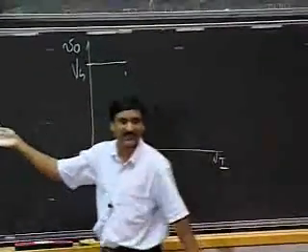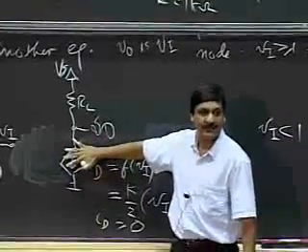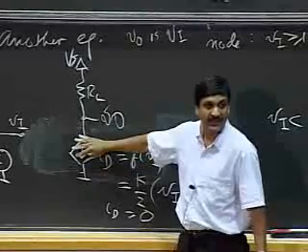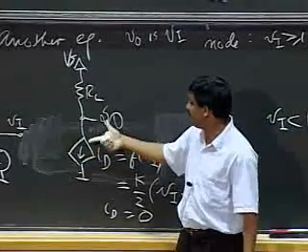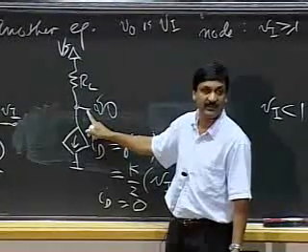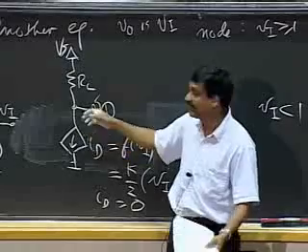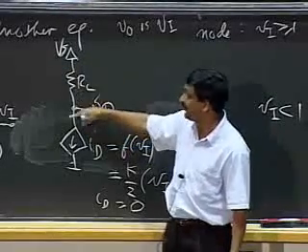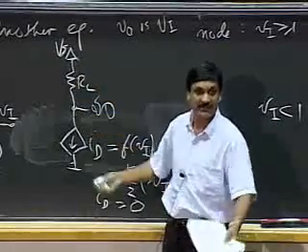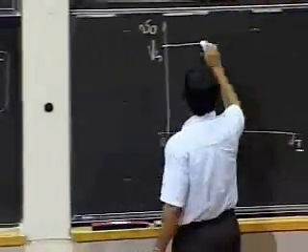Okay, that makes intuitive sense, right? As long as the current here is 0, this is like an open circuit here. If this is an open circuit, then effectively V0 is simply the voltage Vs. V0 simply appears here. Okay, if you want to grunge through KVL and KCL, go ahead. Vs minus RL times the current is V0, and the current is 0, so it's Vs. So this is simply Vs.